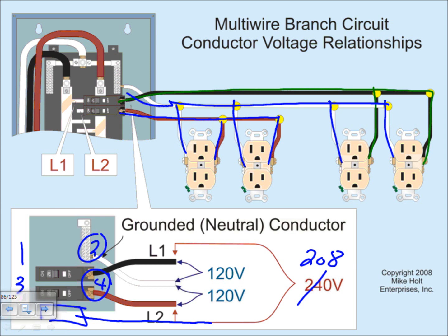Any questions, guys? In a single-phase system, if this circuit pulls 10 amps and this circuit pulls 10 amps, the current coming back here is 0 amps, as you guys know. The way the single-phase system works, if 10 amps are going, they go against each other and magnetically cancel the effect of each other.